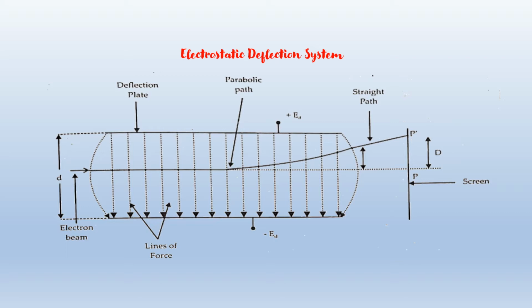In a CRT, two pairs of deflection plates are used. Input to be displayed is applied to vertical deflection plates. Generally, a sawtooth voltage is applied to horizontal deflection plates. The final change in the direction of the electron beam depends on the combined effect of both.